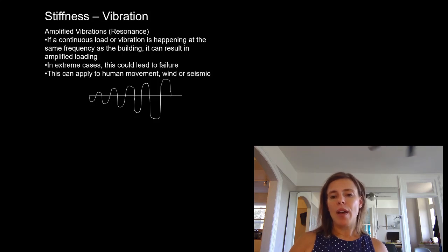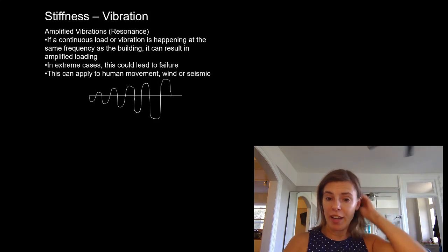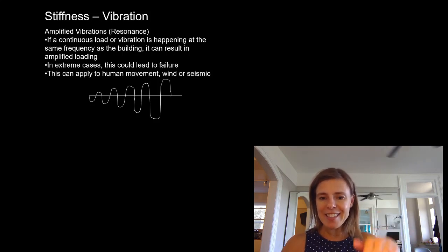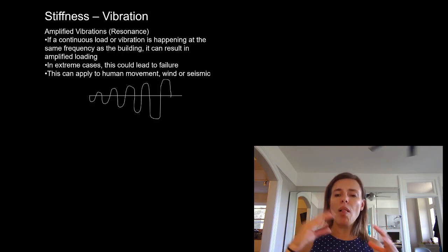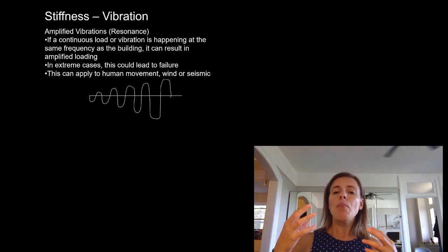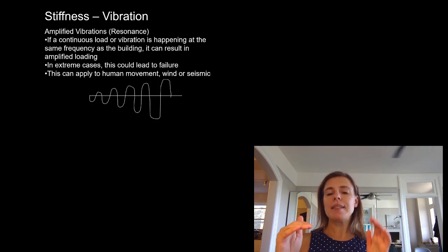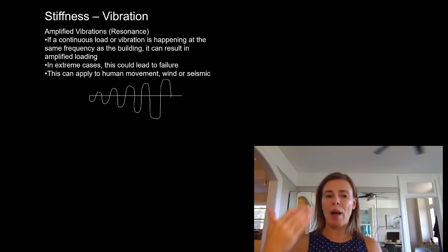If you've ever been walking on a pedestrian bridge while someone else is running on it, you feel their transient vibration and also a little bit of amplification, because the runner can start to get into a vibration with the bridge, and you can find it very discomforting. So all of these things are why we think about vibration. The rarity is that we're worried about failure. Mostly we're worried about comfort. So we look at you stimulating the thing and causing vibration, but then we also look at someone else walking by you and causing vibration, and how that makes the people around them feel.